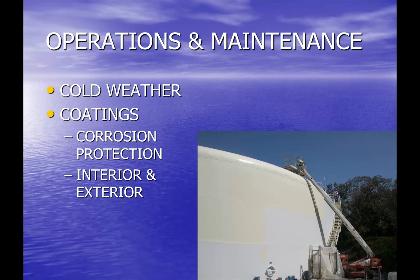I mean, you're talking about several $100,000 to coat the interior of a reservoir, and there are all sorts of regulations you've got to deal with, from maintaining compliance with NSF standards relative to the contact of a coating with potable water, as well as some of the AQMD standards. And that's kind of a moving target. I've had a coating manufacturer representative show up in my office multiple times telling me, hey, this particular coating material, if you're interested in coating a reservoir, you've got to do it soon because it's not going to be available after a certain date because it's getting regulated out of the market. So you've got to keep an eye on what is meeting current standards anytime you're looking at a material like that.